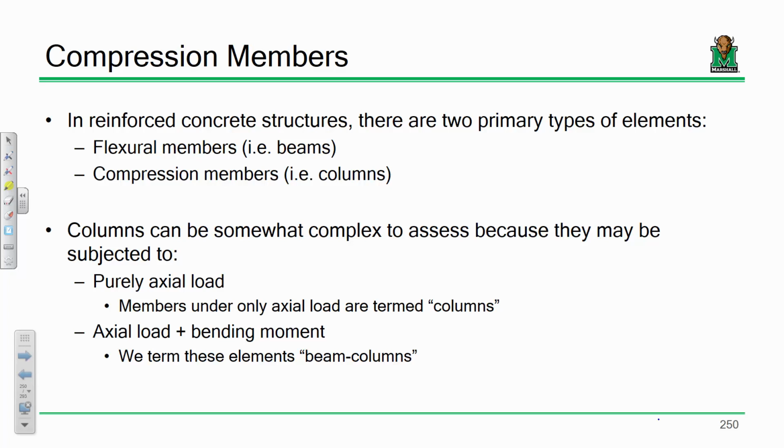That's a mechanical property I'm talking about. Tension-controlled beams are ductile. Compression-controlled beams are what? Brittle. And when things fail brittly, they fail like that. Here's the thing when it comes to columns. Is there any tension in a column? No, it's just being pressed on.